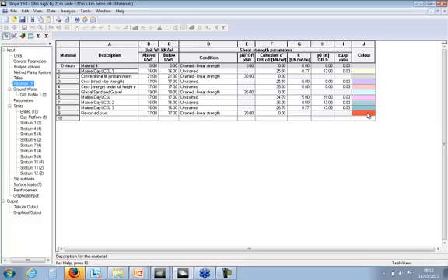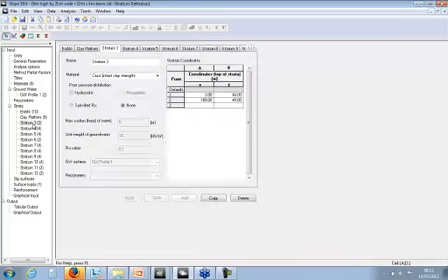You can change the color of the material for your outputs. You've got a groundwater profile, you can put piezometers in there. The strata information is inputted in terms of coordinates, and often we use, for example, CAD plot to plot the coordinates and then put that in here. But Oasys is actually working on a direct DXF input.